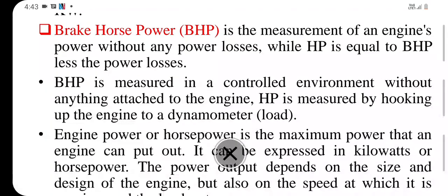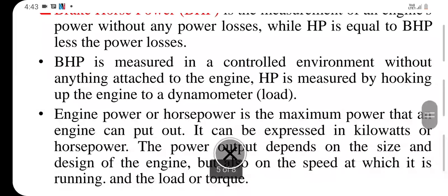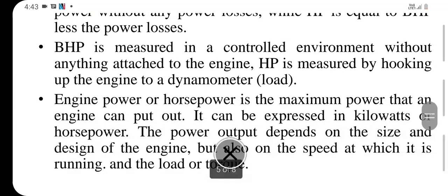HP is measured by hooking up the engine to a dynamometer. A dynamometer is a device used for measuring torque. Engine power or horsepower is the maximum power that the engine can put out. It can be expressed in kilowatts or horsepower.